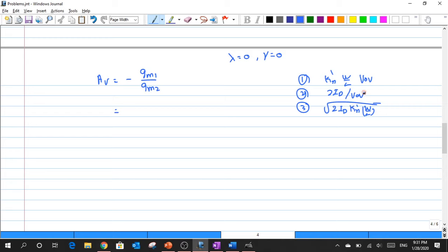Now one can see that we cannot use the first form, for the reasons I said during the class: there is no particular parameter that connects both the transistors. What connects them is the current, because the current that flows through M1 and M2 is the same. So I can use either of the other two equations to compute this gain ratio.